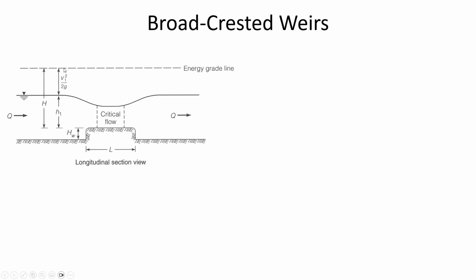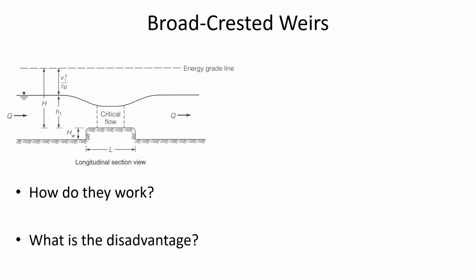So they're picturing it here prior to the critical flow, when the water accelerates and flows at the most efficient depth over the obstruction at the critical flow, then relatively speaking, more of the energy would be wrapped up in the energy grade line. And by the way, this is not to scale, because remember, what we've already learned is that when we have a rectangular channel and the water's flowing at critical depth, the velocity head only represents 1/3 of the specific energy.